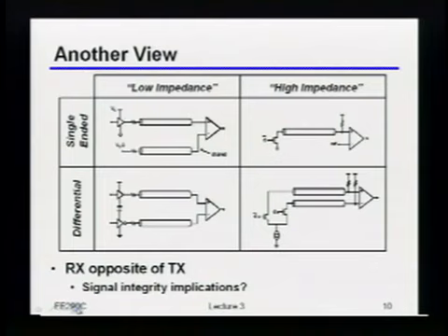So notice, for example, in this design here, I may have added these explicit resistors in my voltage mode drivers there. So I've maybe got 50 ohms right here. But on this side, I've left it open circuit, okay? Similarly, in this current mode driver over here, I've said, okay, I'm not going to put a resistor on the transmit side. I'm only going to have it on the receive side. So my transmitter actually looks like an open circuit driver. And on the receive, I just put some resistors there to grab that current and convert it into a voltage, okay?